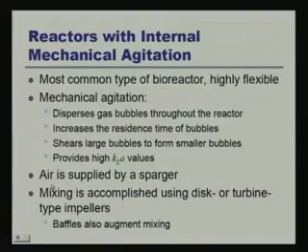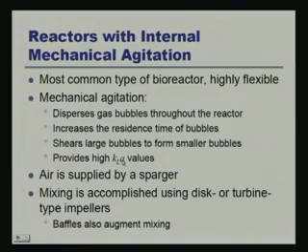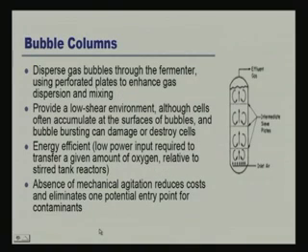At a constant airflow, the mass transfer level is increased. Air is supplied by the sparger in such a reactor system. Mixing is accomplished using a disc or turbine type impeller, and baffles also augment the mixing. And the next reactor system, as I have also discussed earlier, is the bubble column